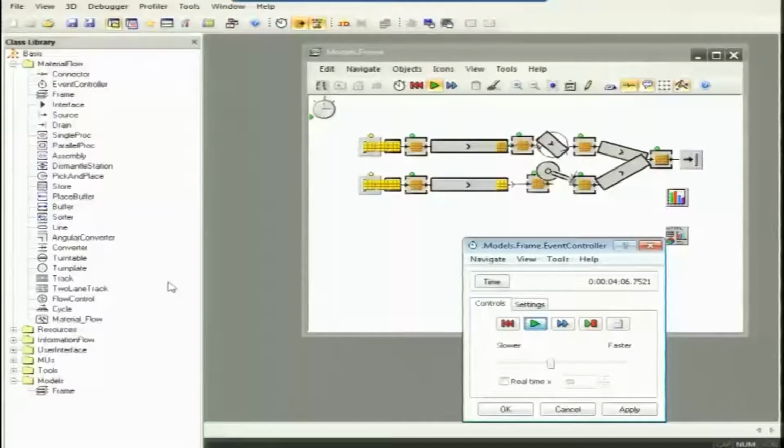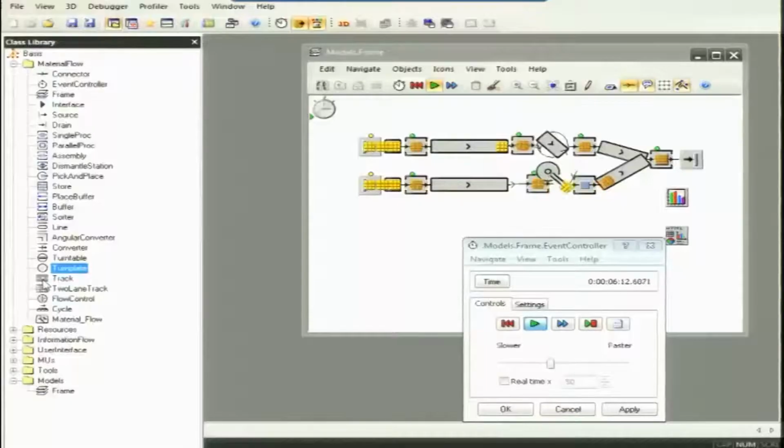Similar to the turntable, we can have a turn plate. We can put one piece in each direction in a turntable. It is a single direction turntable that is being shown on the screen. With a turn plate, we can have one plate and put multiple workpieces on it. It is like a rotating dining table that we have. We put the dishes over there and we can rotate it. We can pick whatever workpiece we like from in between. So the turn plate is done.